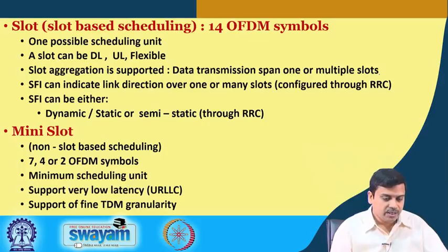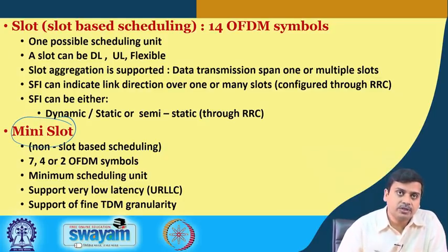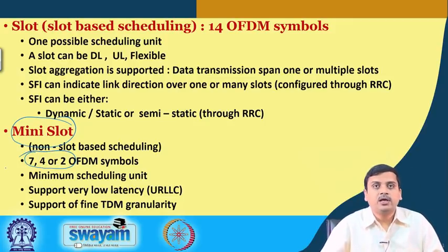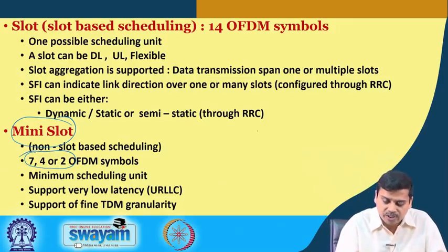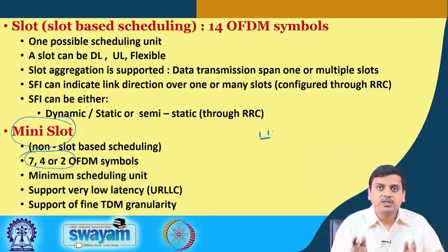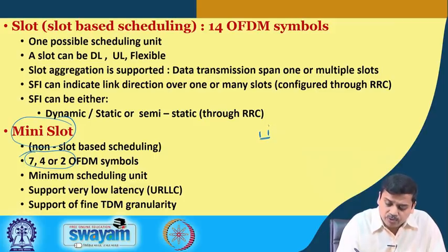Further, we will also see that when we go to this new generation system, there is a provision for mini slots, compared to only the subframe or the slot duration for mu equals 0, which can also be addressed. And these mini slots can be of 7, 4 or 2 OFDM symbols, meaning that within a very short burst, one can say this is the entire transmission unit. So, if the burst is short, decoding time is also short, and response time becomes short, because the total response time is counted in terms of multiples of this transmission time.